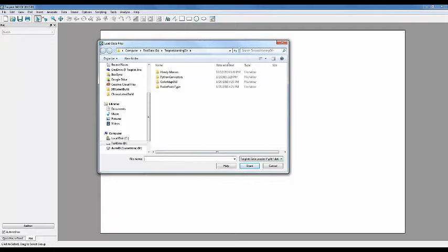And again, these data files are in this directory. You'll notice that there's a Mach 0.8, alpha 0, beta 0, and there are several data files here, combined, which is a PLT format. For those of you who are unfamiliar with Tecplot or less familiar, PLT files are typically binary. They tend to be both smaller and load significantly faster.